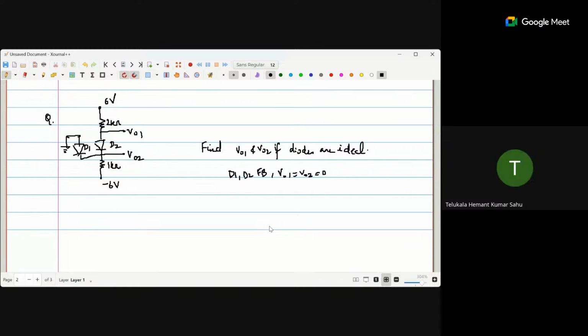The voltage difference will be divided, ma'am. Correct. This circuit will act as a voltage divider only when D2 is forward biased. Am I right? Yes, ma'am. And when that happens with D2, then you check the status of D1. That is the way to do it.